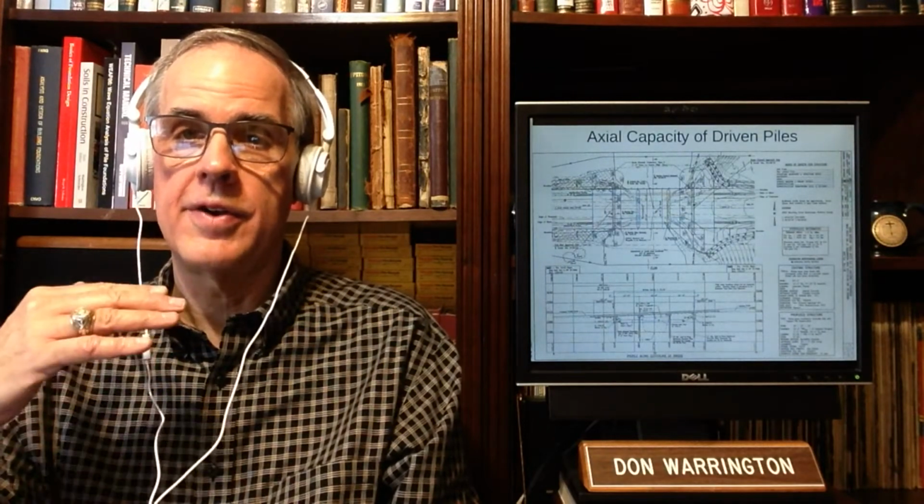Your materials, anybody who's been involved in pile driving knows that steel, concrete, and wood don't drive, quote unquote, the same. They have different densities, acoustic speeds, flexibility, all kinds of stuff. That means that they drive differently, they have different effects of the hammer, they have to be handled differently, either during setup, setting the pile into place, and during driving. So there's a lot of non-uniformity in that.